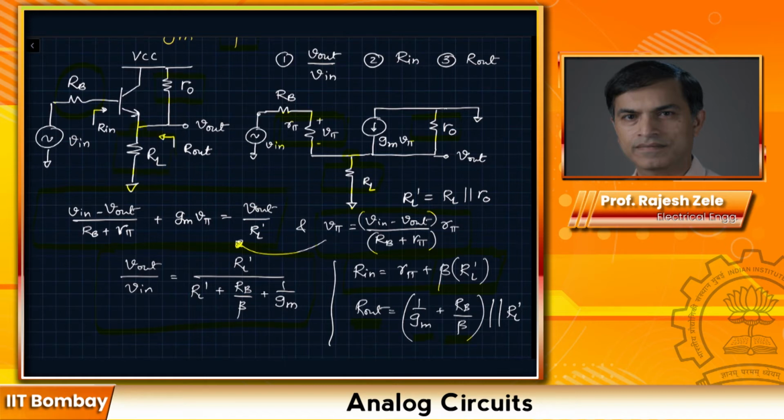Okay, this may be too much to digest, but you need to really go through the analysis by yourself and convince yourself. What we will be capturing eventually is all these rules of thumb. For example, one rule of thumb is any resistance at the base, that resistance will get divided by the beta of the transistor when we are looking at it from the emitter point of view. And any resistance at the emitter looking outward will get multiplied by beta, which is what we saw over here. So that's the rule of thumb that we come back with.